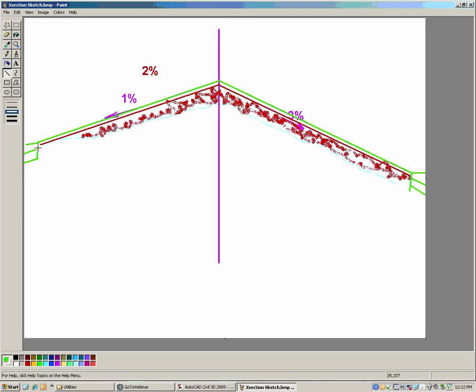The reason we need to have 3 profiles is because I need to make a surface that is the top of this leveling course, so I can set my overlay and widening assembly on top of that. So with those 3 profiles, it gives me the ability to control, pick a different color, it gives me the ability to control this point, and this point on that surface. So I can make minor adjustments to achieve this minimum 2% grade and then raise up the right-hand side of the road, okay?